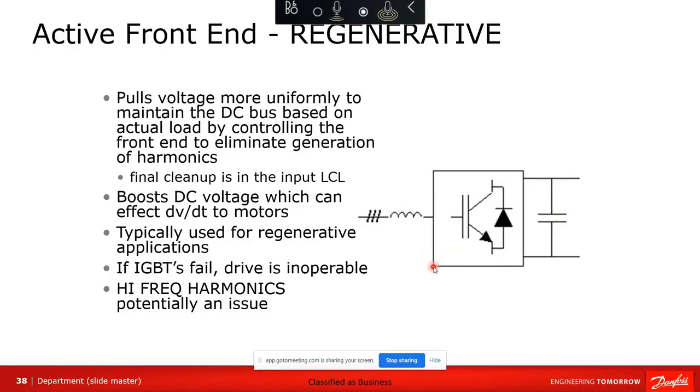There is another thing to consider from a harmonic standpoint. IEEE typically goes up to the 50th order harmonic. And let's see, 6 times 5 is at 3,000 hertz. When you get into high frequency harmonics, and this is high frequency switching, it doesn't address that. And there are some issues with high frequency noise in systems that can have some problems. So things to think about.